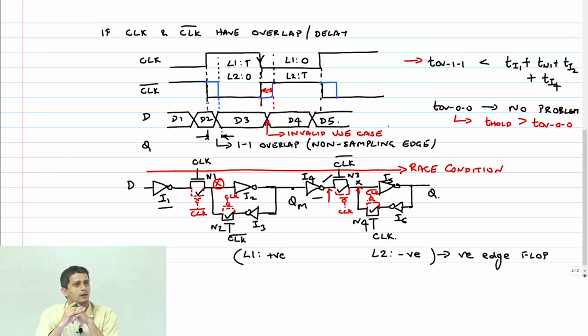Okay? Any questions here? Yes. This is the minimum hold time that you will see in a flop, and the hold time origin is basically clock overlap. Okay?